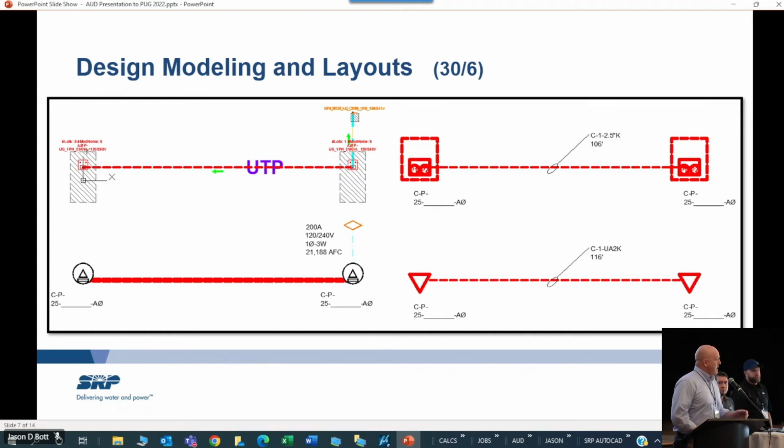And our cable length is our conduit length plus we include 5-foot spoil for termination on each end. So in that 100-foot length, you're actually consuming 116 feet or plus or minus of wire. You can configure that however you want. And so we do it slightly different depending on the device that we're connecting to, okay?